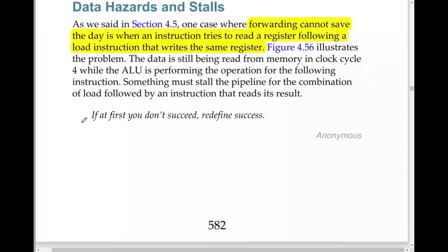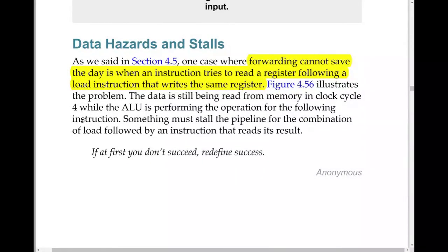Now the next thing is data hazard and stall. Till now, whatever I have explained, it looks like if there is a forwarding logic control unit, then everything can be resolved by forwarding. But that is not the case, right? I have explained in the last class that if there is a load instruction first and then an add instruction, then you cannot resolve it using forwarding.